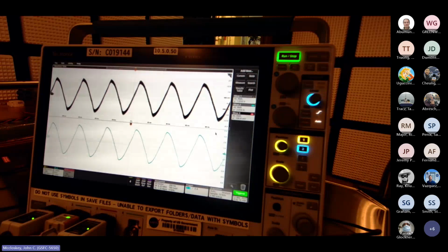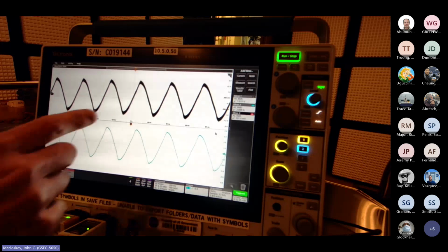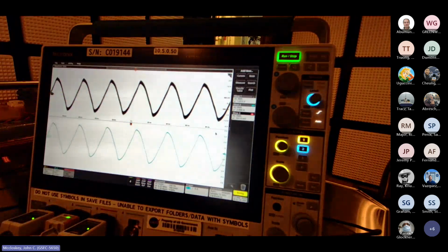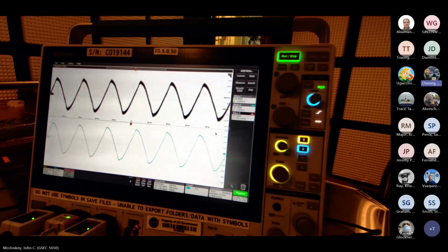Okay. But the entire point of the pre-calibration exercise is to record the signal generator setting for what it takes to get your desired limit, in this case, the default 1 volt RMS, across your calibration resistance. Okay, everybody clear on that? Yes, sir. Okay. And I'm going to record the current too. And current's kind of extra credit.